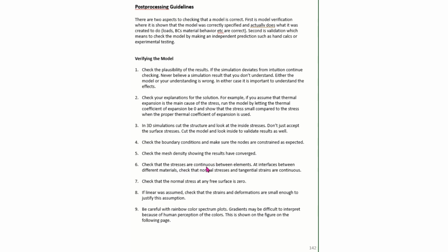Check that the stresses are continuous between elements. At interfaces between different materials, check that normal stresses and tangential strains are continuous. Check that the normal stress at any free surface is 0. If linear was assumed, check that the strains and deformations are small enough to justify the linear assumption.